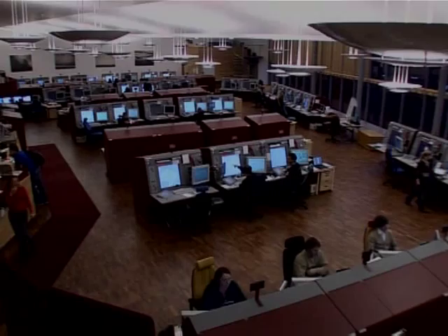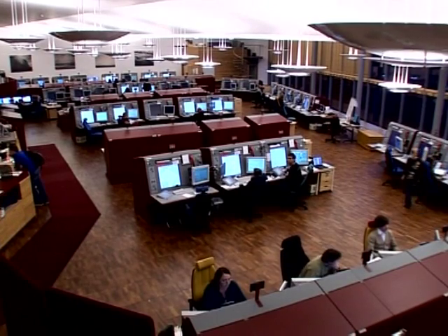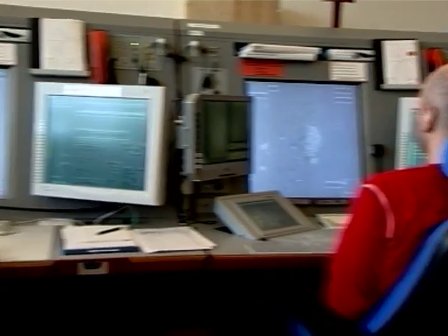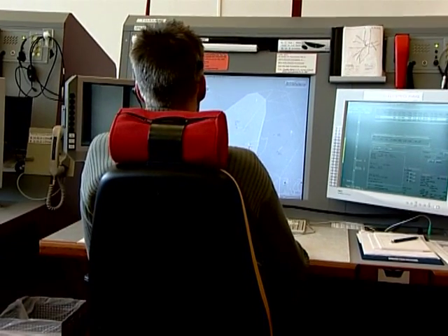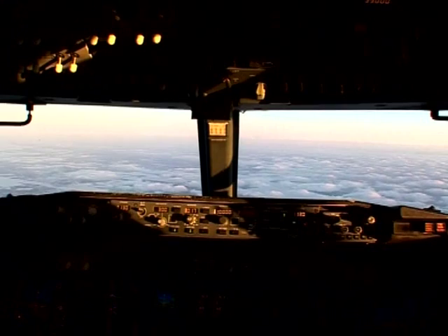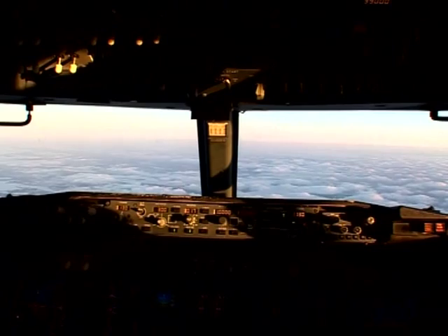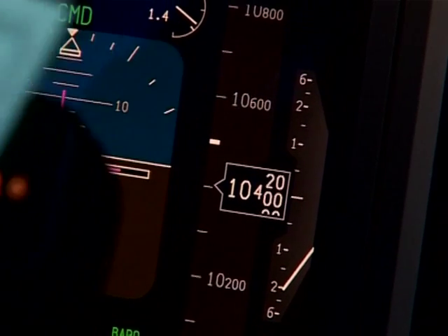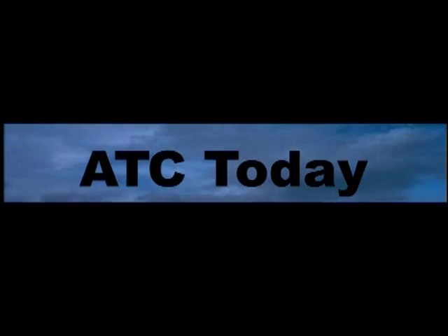If we look at the current air traffic control system, everything is done based on radar surveillance and the predictions based on the radar. And the time span becomes very short. You're normally working in 2 to 5 minutes look-ahead time. What we do today is basically fly as fast as we can to get to the airport and then arrive there to find out that there are too many airplanes, so you have to put them in a holding pattern.